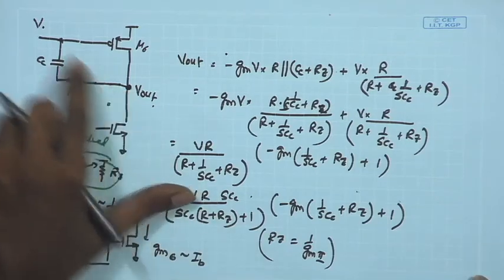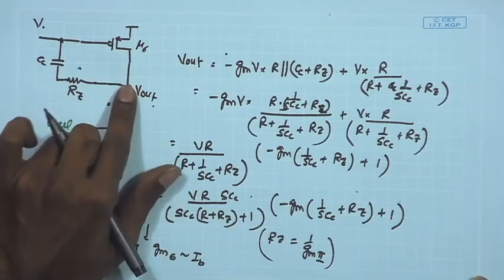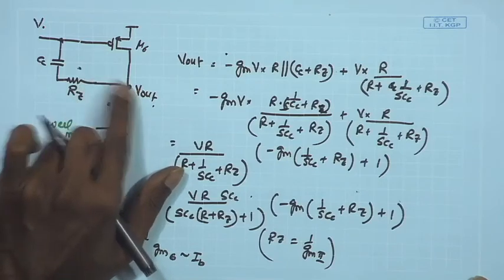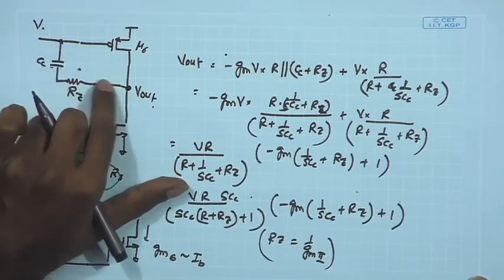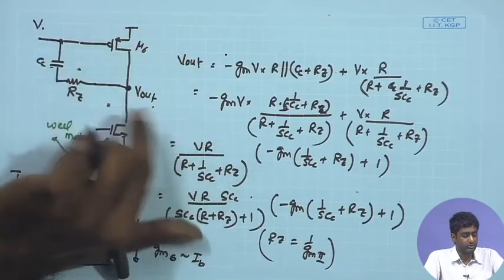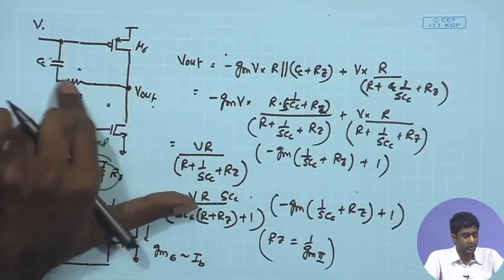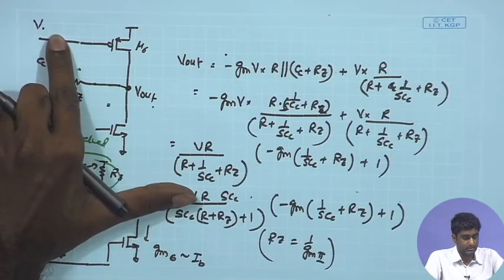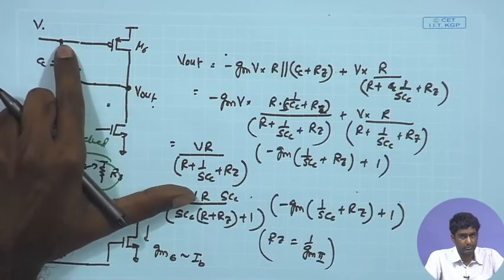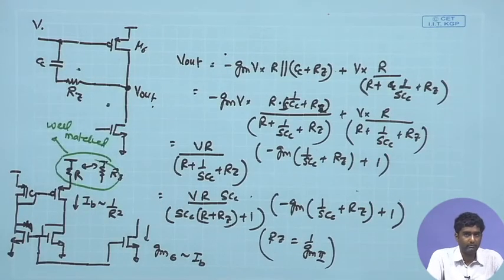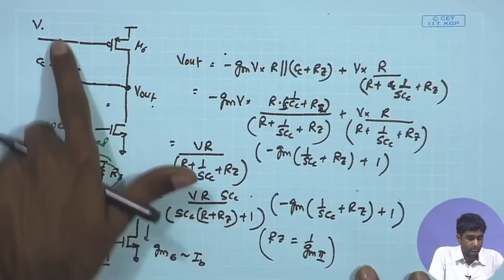So, here also if you see, ultimately this is a shunt configuration. Output is sensed using a shunt connection, V out is being sensed, so shunt, and at the input side you are again mixing current. Although the entire scheme is a voltage to voltage converter, whenever the feedback signal is mixed at the same terminal as the input quantity, we have a shunt at the input also. So, you have a scheme which is similar to what we had in the op-amp, and we use that large RF to bias the input node. So something similar over here.